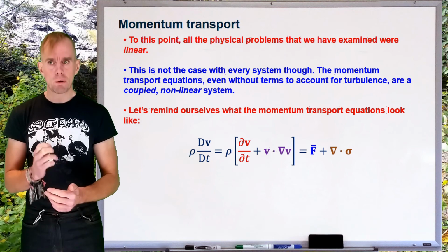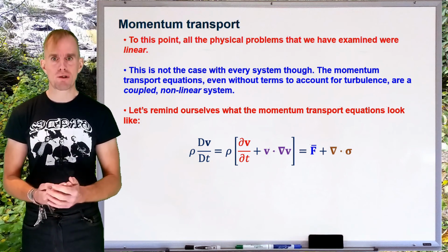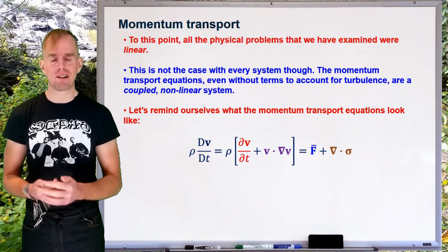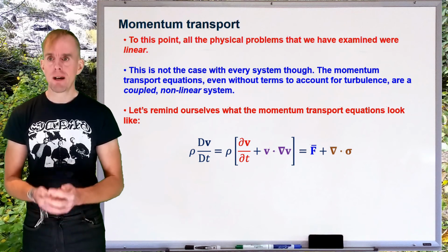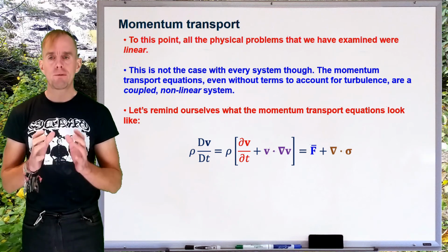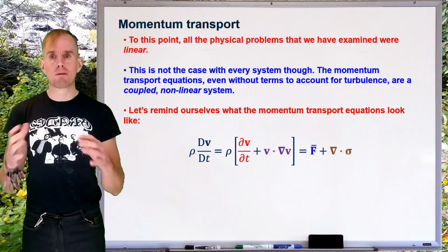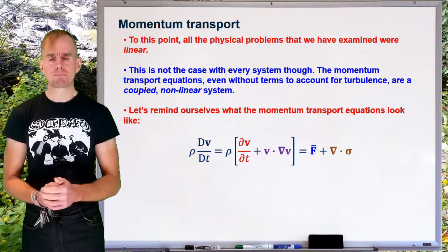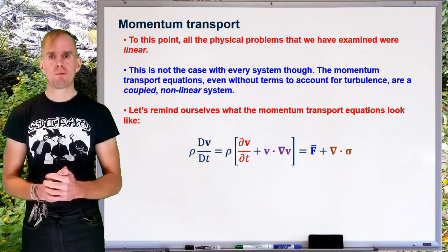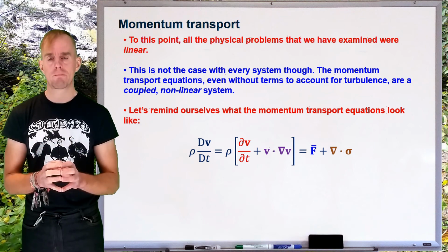Now this is quite important, because when we look at other terms in this equation, we have to make sure that when we substitute for them, they are dimensionally consistent. None more so than when we look on the right hand side of the equation at the force terms. The left hand side of this equation physically is the rate of change of volumetric momentum. The right hand side are forces that can give rise to that momentum change.